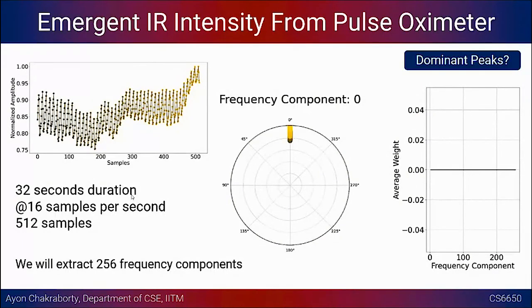So you might not have the flexibility to wait for 32 seconds and then give the data set to the system. Often these systems are built in real time, right? So it has to operate on streaming data. In that case, you have to continuously run this operation on a queue. You have a sliding window or a queue, and you have to continuously evaluate this entire spectrum, or the frequency components, on top of the queue, right? So in this case, I'm just giving you a demonstration.